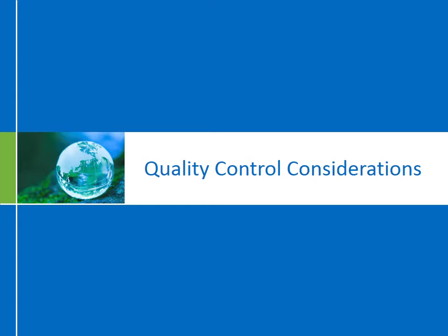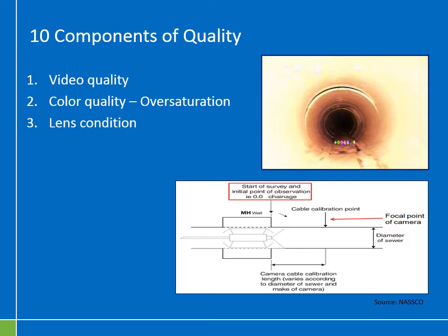So moving from a summary of technologies, what I'd like to talk about now is considerations of quality control as you conduct enhanced inspections. Now for video-based inspection, so we're talking CCTV or HIVE camera inspection, the most important thing to keep in mind is that you need a good quality of video as you go about and do the inspection. Poor quality video is not going to give you the data that you need to make engineering-based decisions on what to do about a defective or damaged culvert.